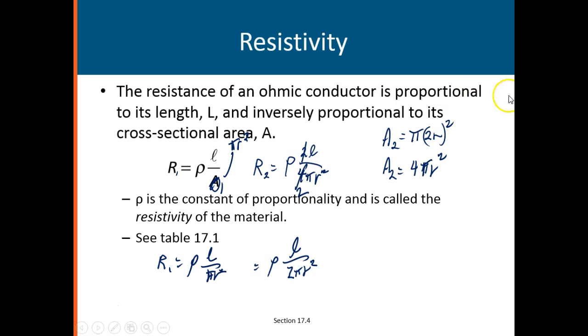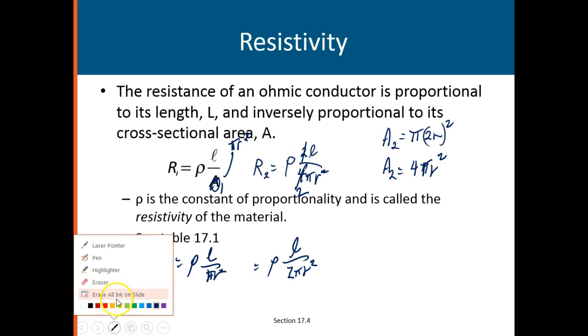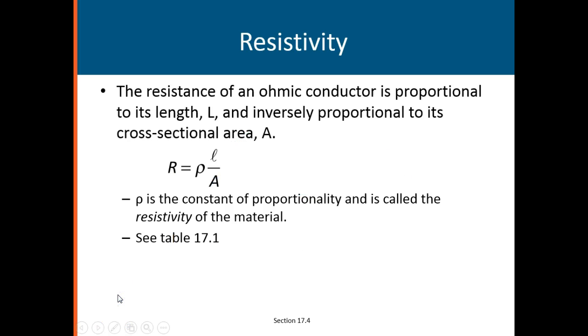Basically, these formulas here. The resistance of that wire, the rho is the same. They're both nichrome, right? The size of the wire is the same. The areas are the same. All you've done is double the length, right?